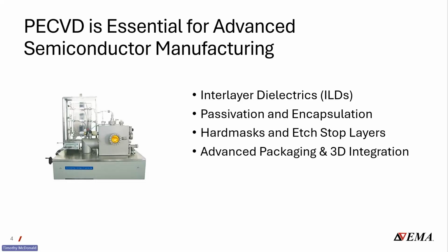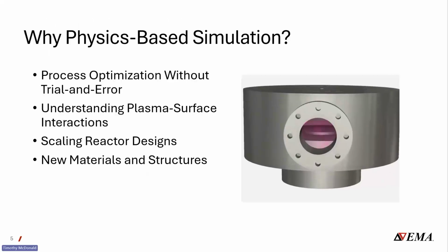Advanced packaging and 3D integration. Wafer level packaging, TSVs, through silicon vias, and fan-out structures all require conformal PECVD films for insulation and protection.